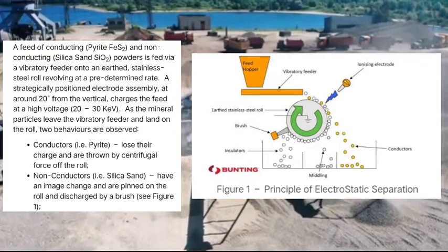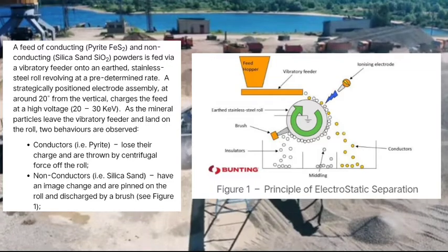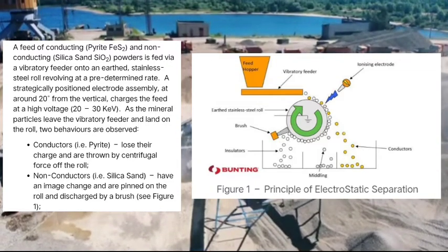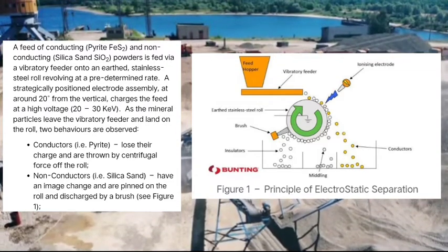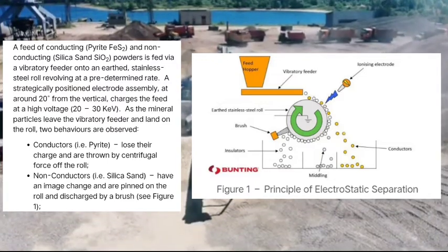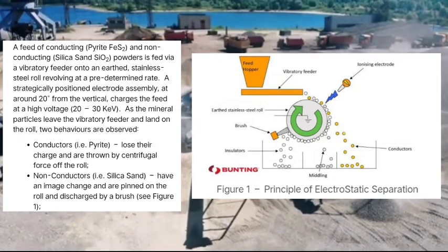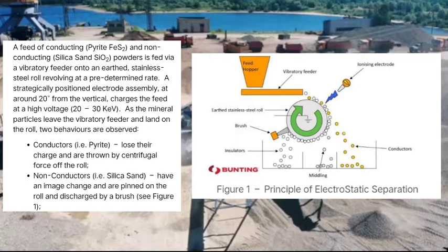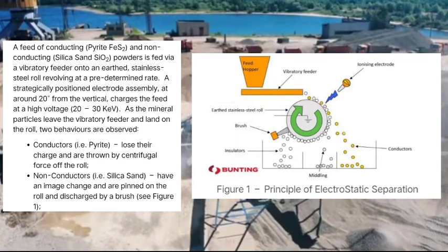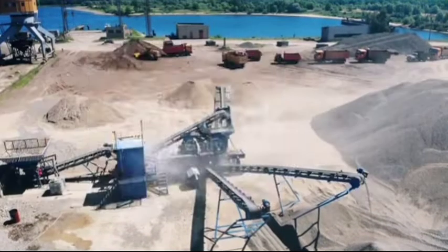As the mineral particles leave the vibratory feeder and land on the roll, two behaviors are observed. Conductors, pyrite, lose their charge and are thrown by centrifugal force off the roll. Non-conductors, silica sand, have an image charge and are pinned on the roll and discharged by a brush.